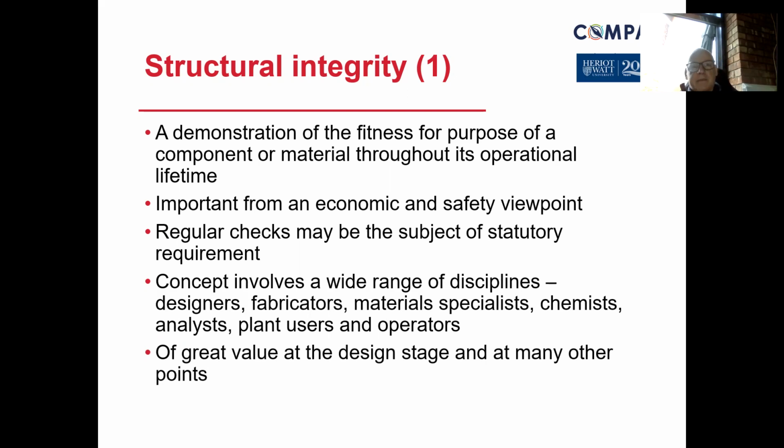So think about your means of escape. All means of escape should, if it's a corridor, for example, leading to a final exit door, offer 1 hour fire protection. Now, we've not just said off the top of our heads that plasterboard can offer 1 hour protection. No, it's been fire tested. Somebody's put it in a lab situation and in a real situation. So they've set up a house kind of room environment and they've put that under fire situations.